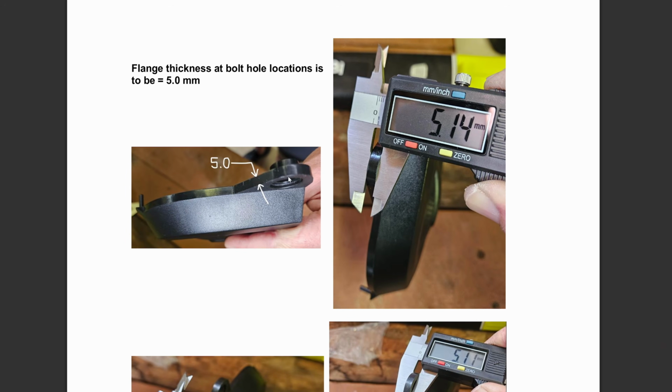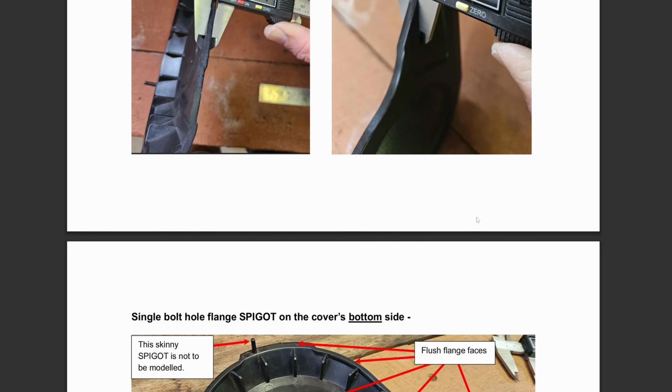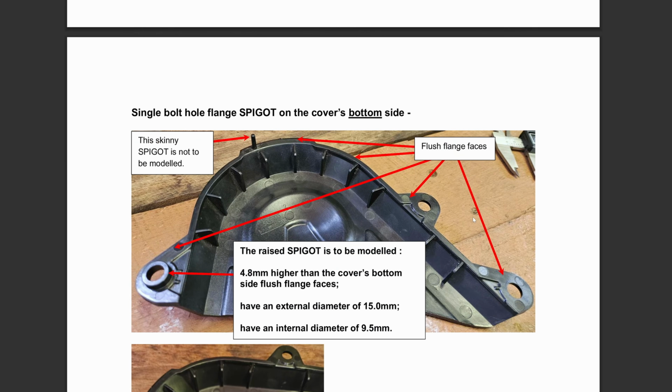Okay, here's what he explained and what he wants me to focus on: the mounting point and the recess. Here the thickness is 5 mm. He also provided a thickness for the flank. So I'll try to make a 3D printable version of this cover.